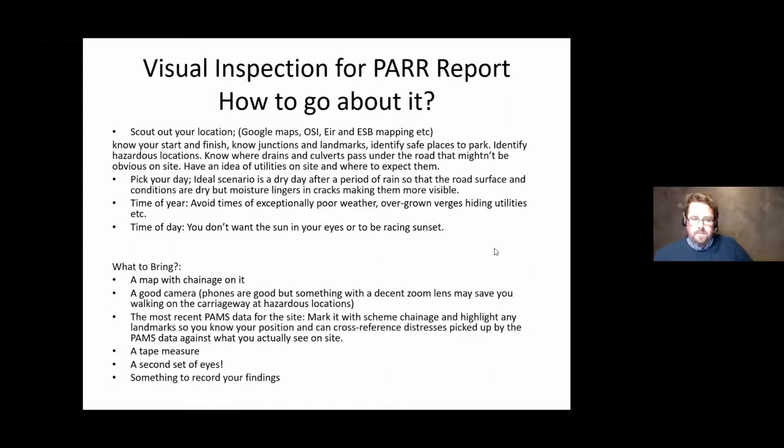What to bring? So again, it seems obvious, but a map with the chainage on it and a good camera. As I've said fairly clearly there, phones are good, but if you have something with a decent zoom lens, it can save you having to actually stand on the road. You can operate from the verge. It's critical for your health and safety.